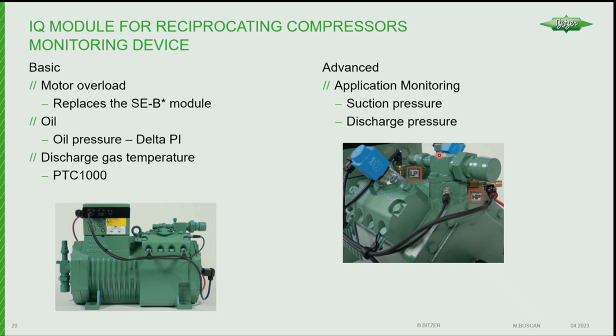We're not trying to control suction pressure at the rack. We're not going to turn the compressor on and off based on some value. And the only time we turn off the compressor with this module is a safety issue. When I say safety, either safety like high pressure or safety like the compressor's on the outside of the application.